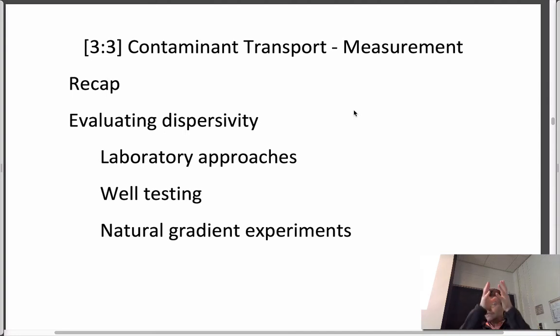It's this Gaussian cloud that starts like a skyscraper and gets progressively wider and wider, but it's because it gets mixed by the tortuous flow paths that it takes and the non-uniform distribution of velocities in pore throats and fractures, etc. And so those are the components we've talked about so far, all applied to transport of conservative species, ones which aren't ultimately sorbed. So that's kind of where we are. We defined an expression that describes that behavior, and that's the advection dispersion equation.